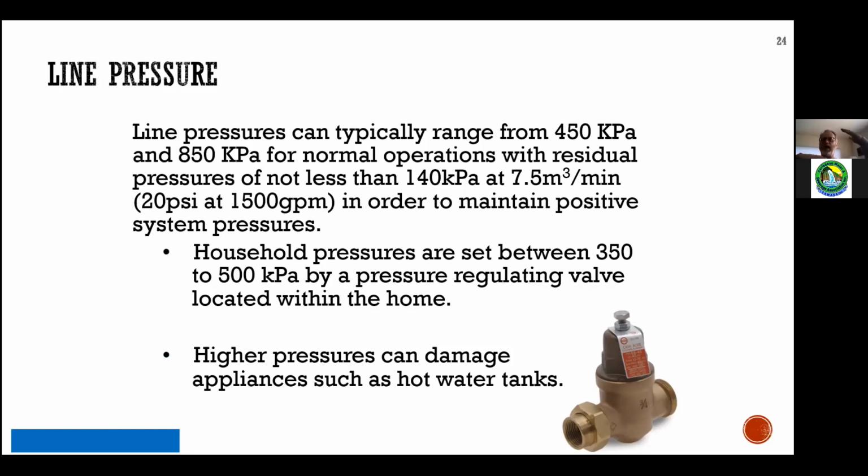There needs to be enough energy to get from point A to point B and any elevation change and still deliver 140 kPa. So engineers will decide what pipe material and diameter needs to be installed. They may need to decide on putting in a booster pump to boost the pressure, because otherwise you don't have enough for protecting water systems in emergencies like fire.